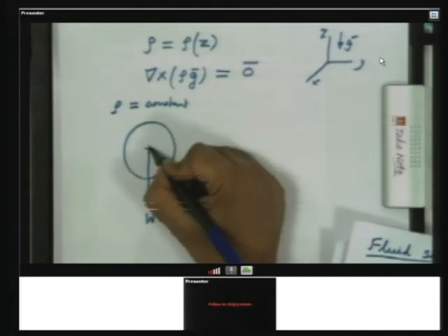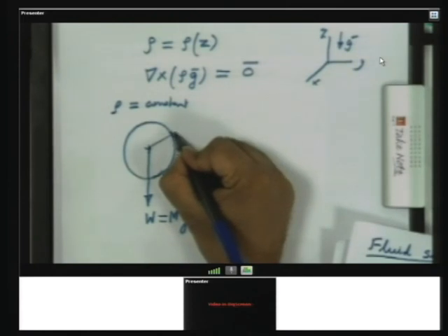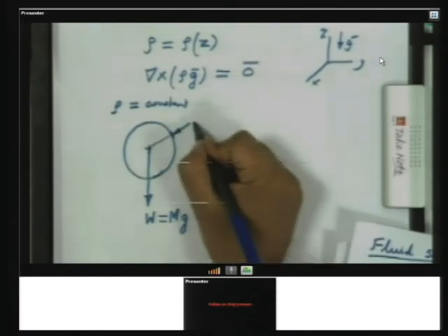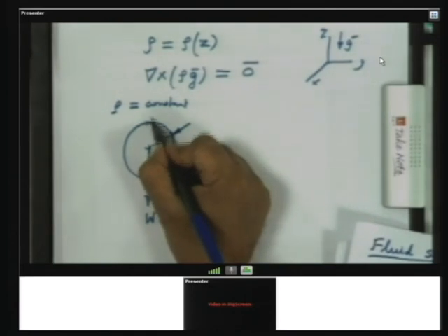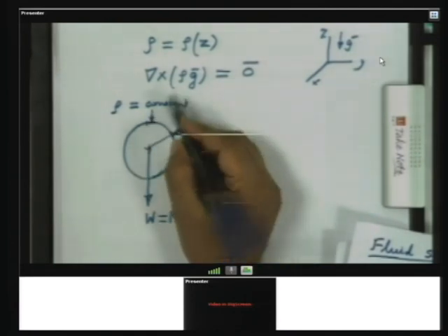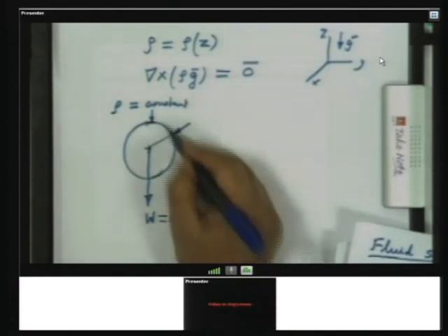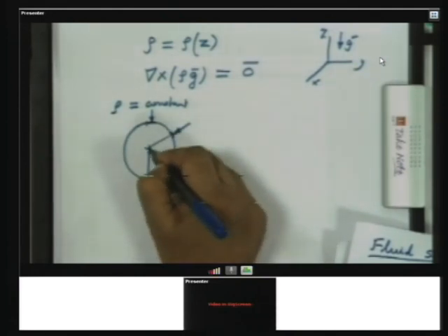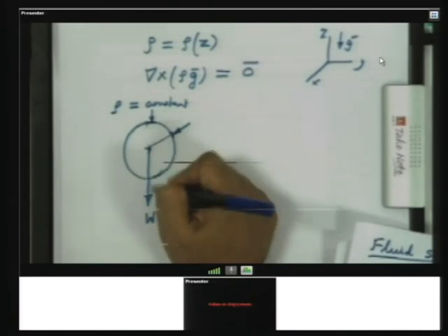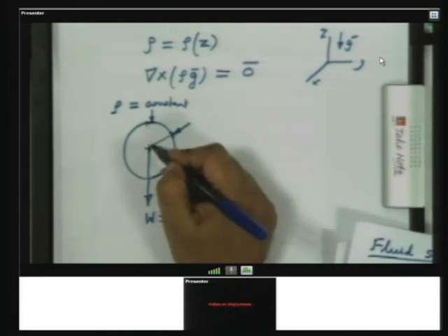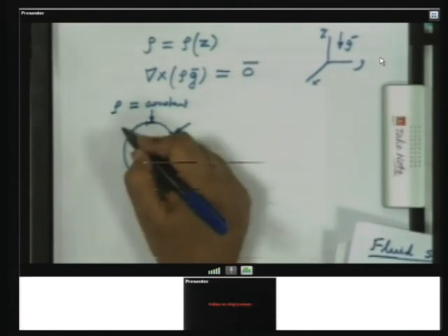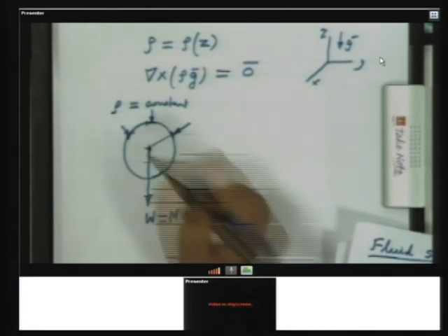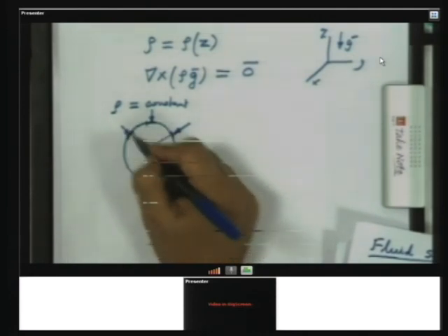So, if I consider at this angle one area element, you are going to have a pressure which acts radially. The normal force is now in the radial direction. So, this P into dA is the force here. Now, I can take another area element here, and the force will be in this radial direction. Now, if we look at the moment about the center, since the weight is a concentrated force effectively which acts at the center of gravity, it has no moment, and all this moment of all these elemental pressure forces, that is also 0, because they all pass through this.